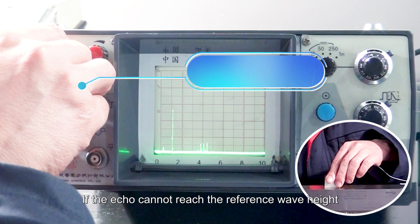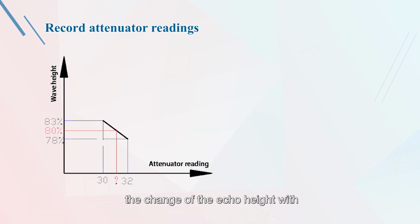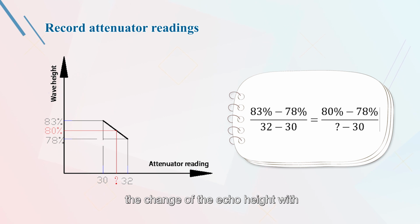If the echo cannot reach the reference wave height only by adjusting the attenuator, the corresponding attenuator reading can be determined by the linear interpolation method, that is, the change of the echo height with the attenuator reading is regarded as a linear relationship.